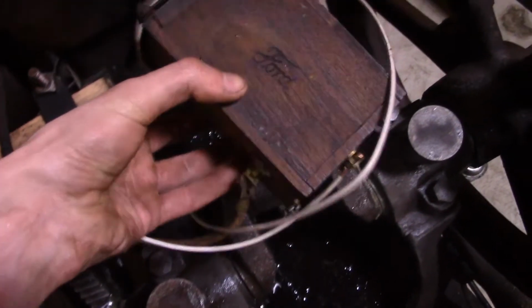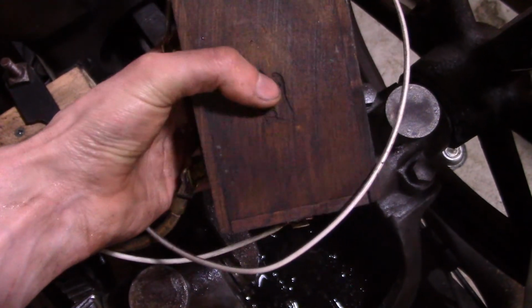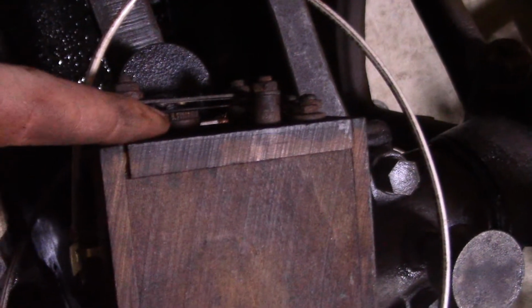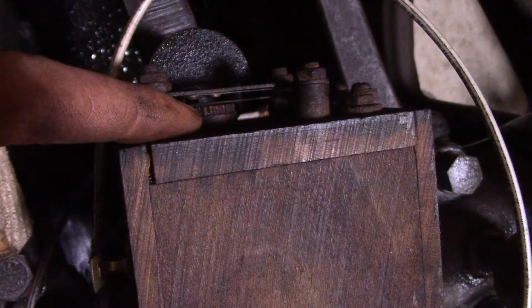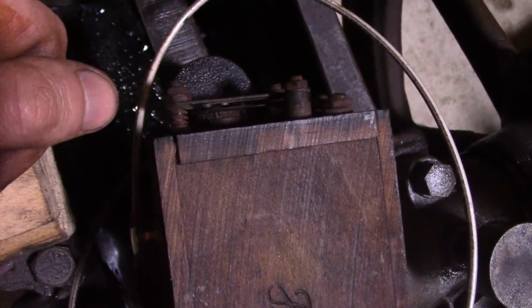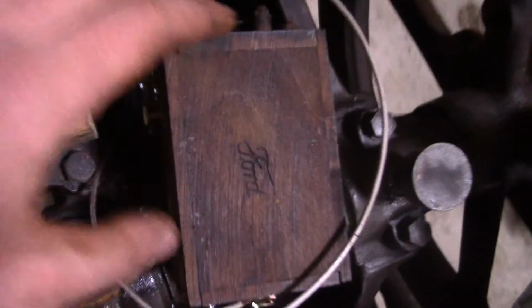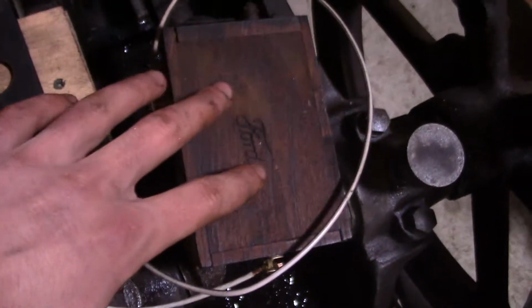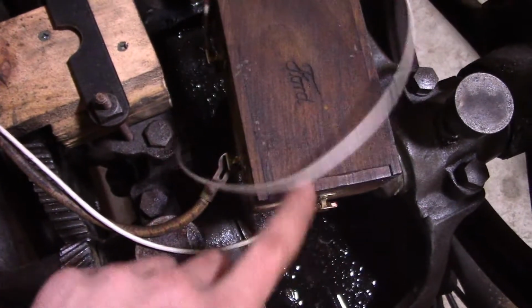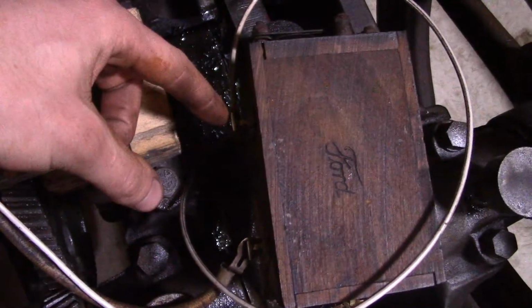This is a Model T Ford buzz coil. Inside it there's a high and low tension coil, primary and secondary. You can actually see the primary coil ends right there. That's the bundle, those little wires there, that's the iron core, and of course that's wrapped with wire. That primary coil, by the way, makes an excellent low tension coil. Anyway, there are 3 leads on this box here. There's a ground, I believe the ground is the bottom. There's the high tension spark plug lead and a battery lead.